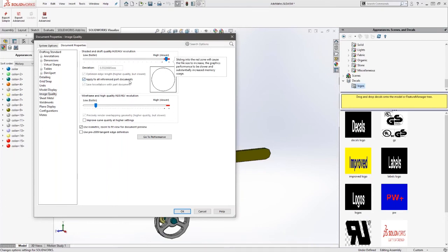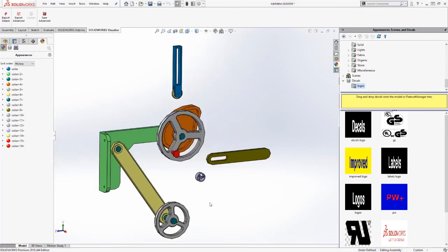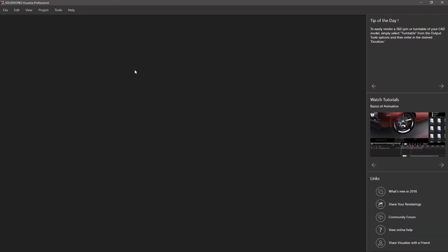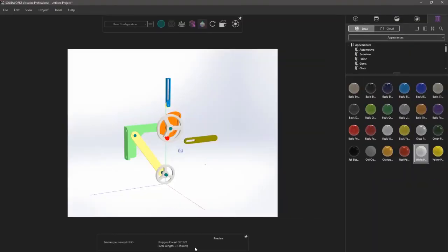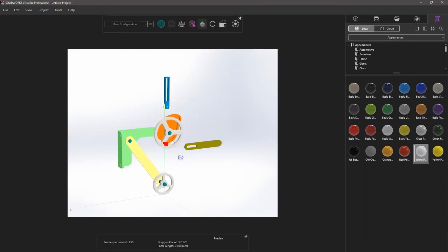So it's a little bit tricky to think about. Okay, so say I do that, all of a sudden everything's going to look really nice, smooth. But if I redo my export, if it's a big assembly, this is going to potentially push you over that edge of, now here in this case, 350,000 polygons, right? 5,000 to 350,000, almost 100 times more.